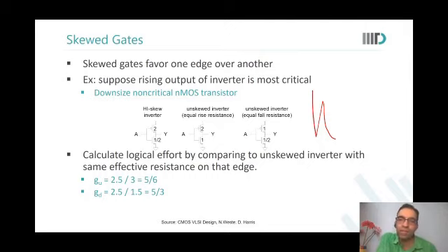So two ways I'm benefiting in terms of rising of Y. One was that the load was getting reduced, so transition faster. But what's the other benefit? In the transfer characteristic, I have shifted this, because I have made the strength of NMOS smaller than the strength of the PMOS. So my switching will happen faster, earlier, at a lower value of A. In fact, at a still higher level of A, I will start to have Y rising, because NMOS will not be able to conduct as much current as the PMOS will be able to provide.